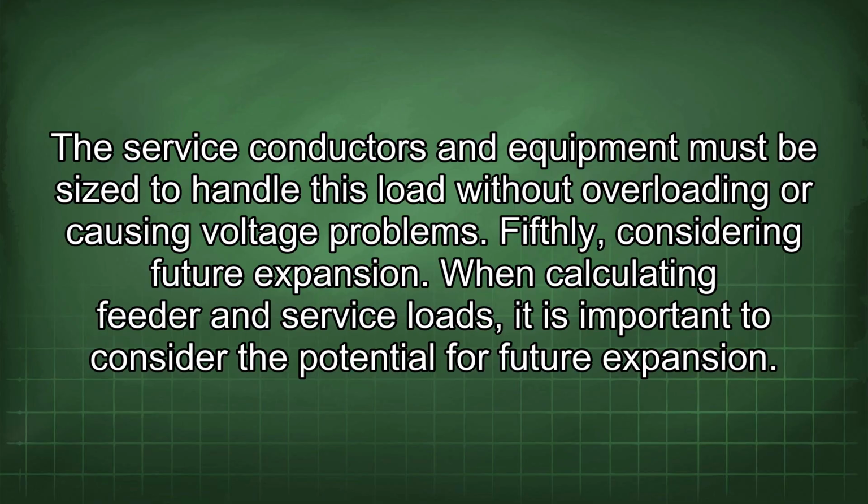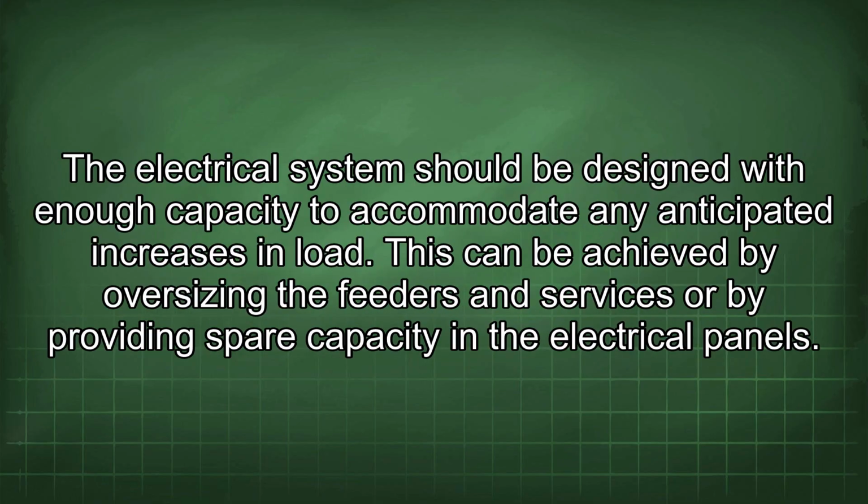Fifthly, considering future expansion. When calculating feeder and service loads, it is important to consider the potential for future expansion. The electrical system should be designed with enough capacity to accommodate any anticipated increases in load. This can be achieved by oversizing the feeders and services or by providing spare capacity in the electrical panels.